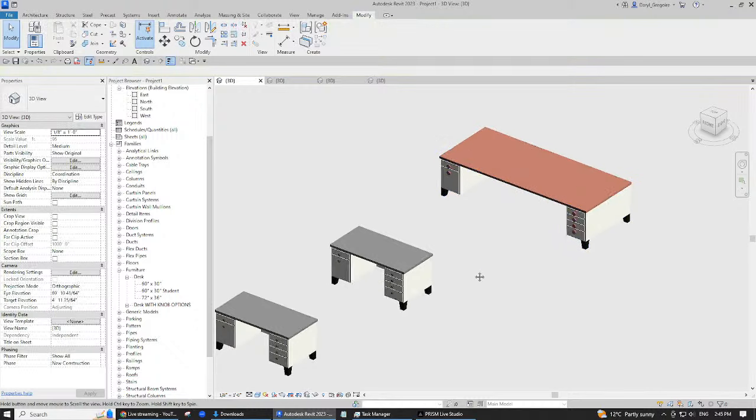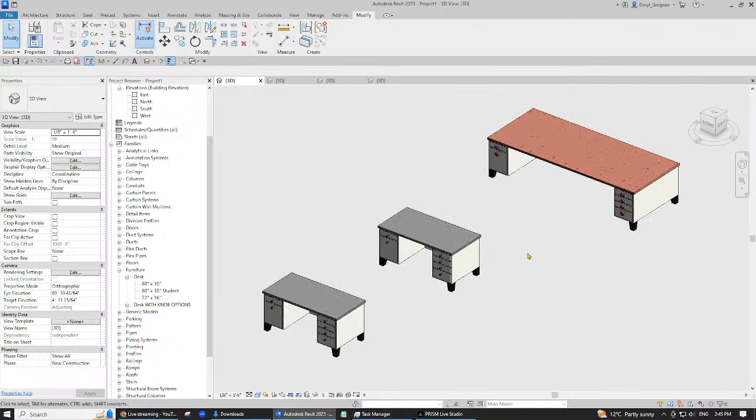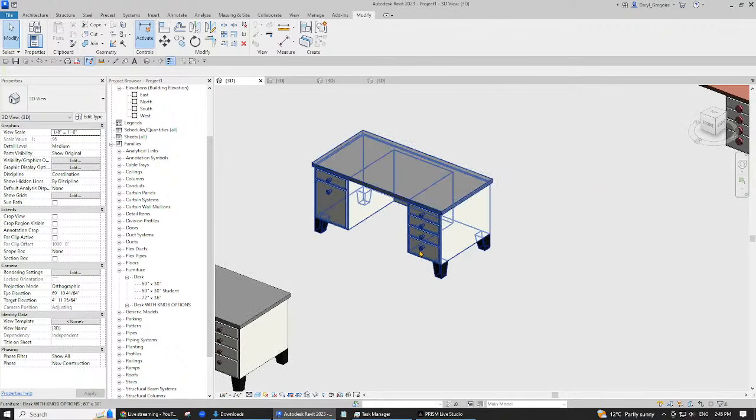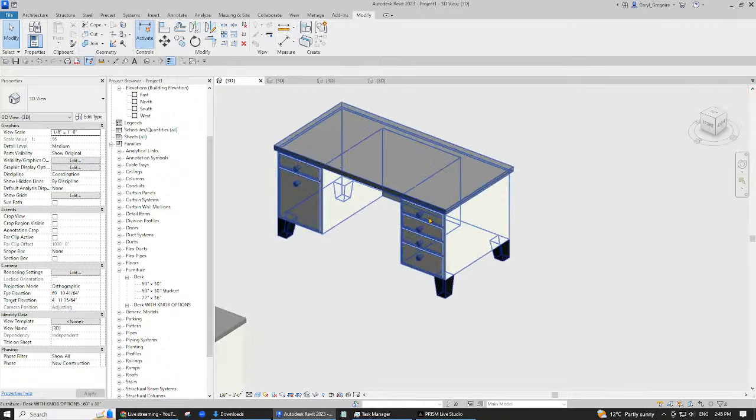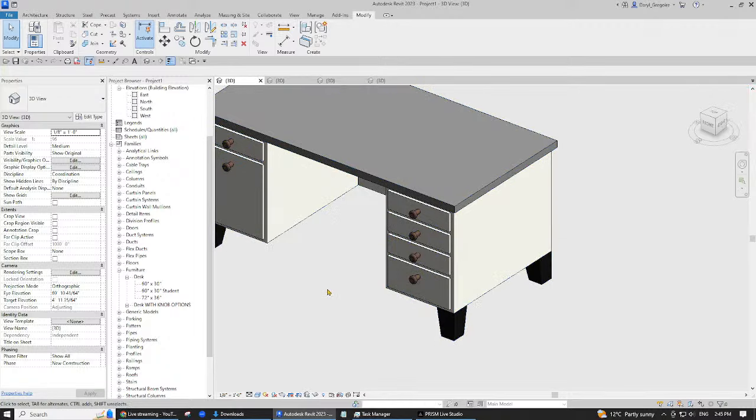And that's just an example of nesting properties and materials. The knobs are individual families that are set separately, then loaded and face-based onto here. Then we had to change them from a generic face-based family to be a category furniture, and then add a parameter in here called knob type and just assign it to furniture.